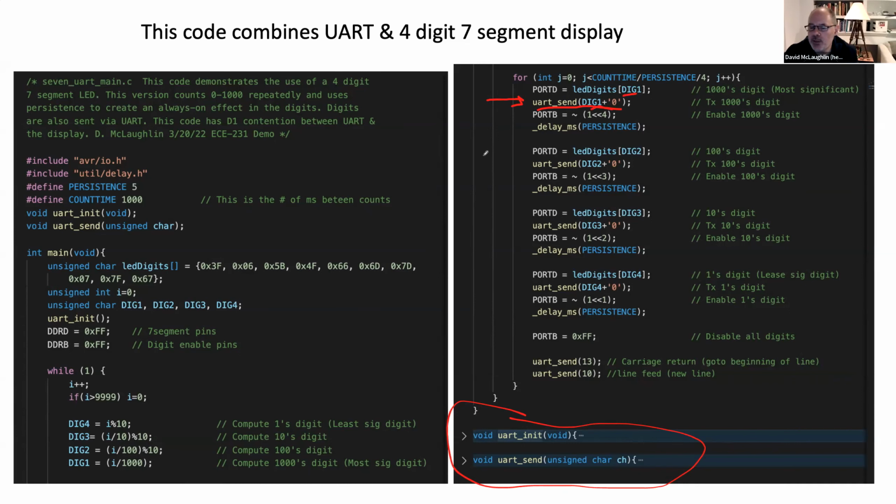But the problem that we had is that since this pin is doing double duty, it's actually being impacted both by our programming the LED and by what the UART's doing. And so that's why we were finding that segment B, because this is, not this one, it's this one, it's PD1. PD1 was the one that went to segment B. So that's why we were having that contention issue.